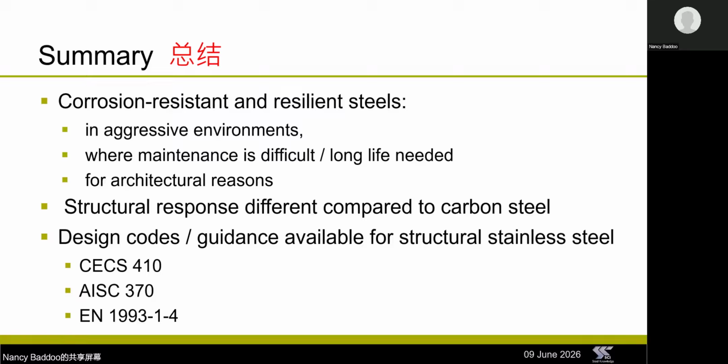You might choose stainless steel in very corrosive environments, by the sea for example, or where you use de-icing salts; in structures that have a very long life, or where maintenance is difficult, expensive, or impossible; and also for architectural structures where the exposed metallic surface finish is very important.